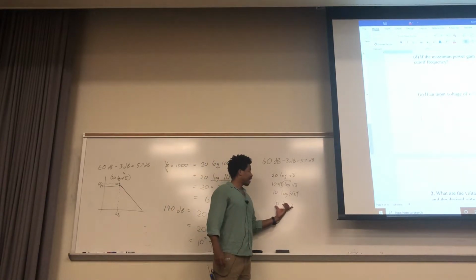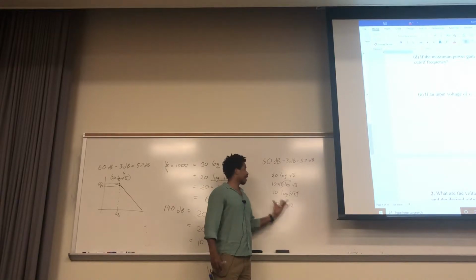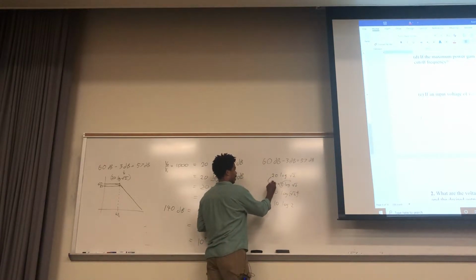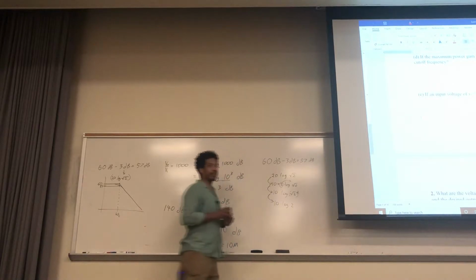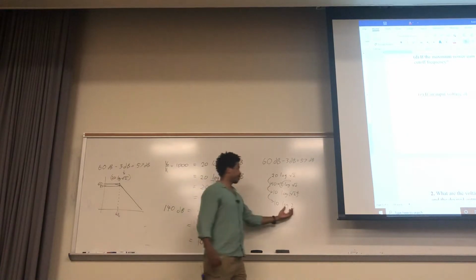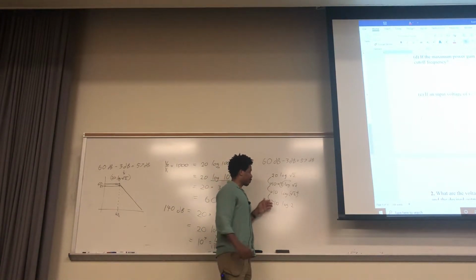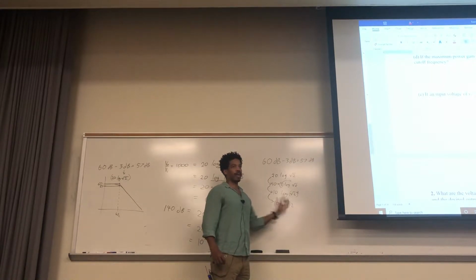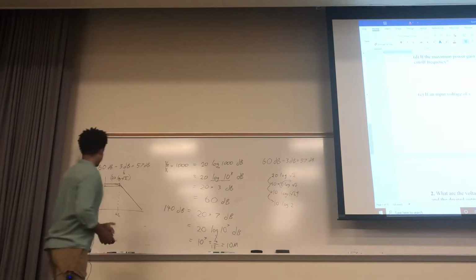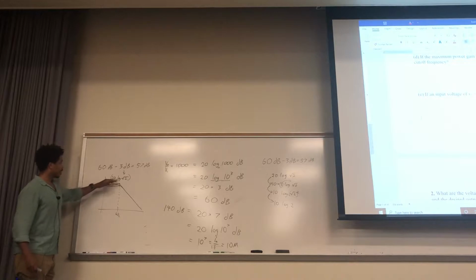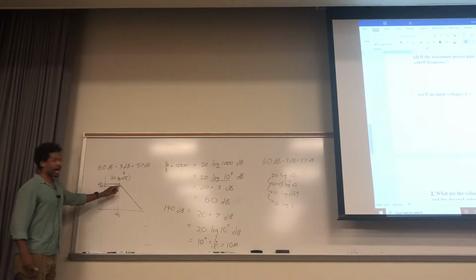But as you can see, this is the equivalence. I started off with this 20 log of square root of 2, but every single step is equivalent to the one above it. So they really mean the same thing. I haven't changed anything, but it just means that in that type of regime, it corresponds to a factor of 2 lower for that cutoff frequency. So still this frequency, right? But if we're dealing with power, that 3 decibels down, you're at 1/2 the power.